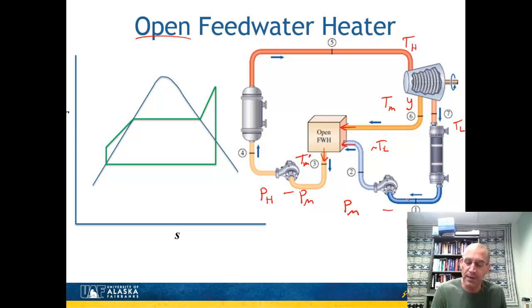So now what's going to be different, we're going to modify this Rankine cycle that I have over here on the left. I've got some new states here. In fact, you see we have a total of 7 states, and we have 3 pressures. And so I think it's really helpful with these is to sketch up isobars that we have. And so that right there would be my P high isobar. Over here would be my P low. And let's put one in the middle